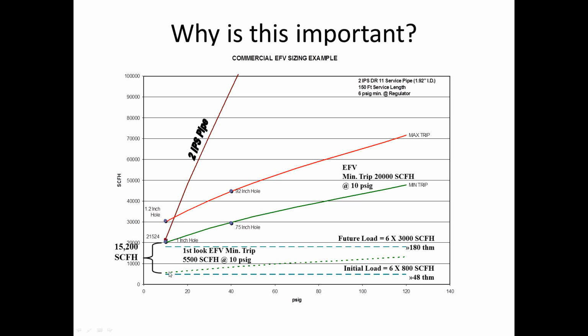We would be above that maximum anticipated load of 4,800 standard cubic feet per hour at 10 psi with our trip point curve.